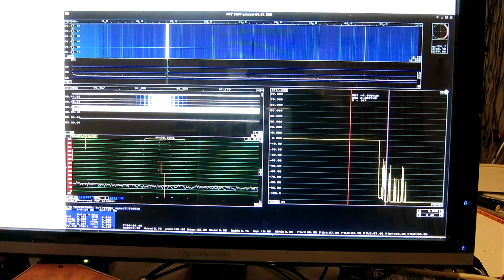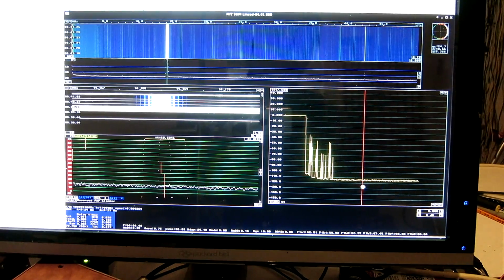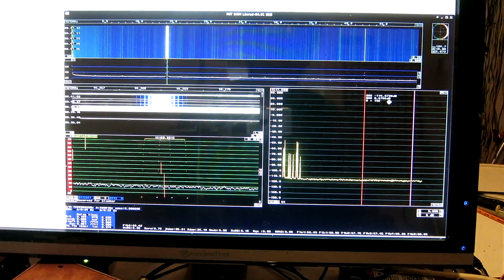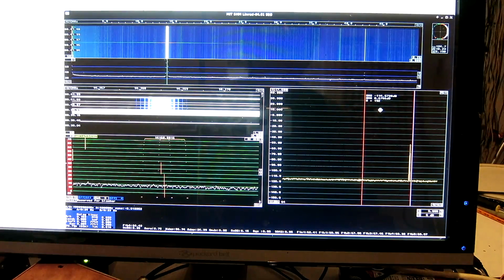And look, what is the level here? About 113. So I get it with some precision like that. Minus 114.57. So that means that the noise floor is 30 dB below this in 1 Hertz bandwidth.